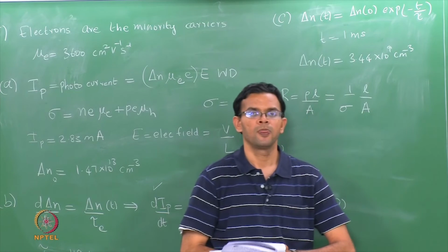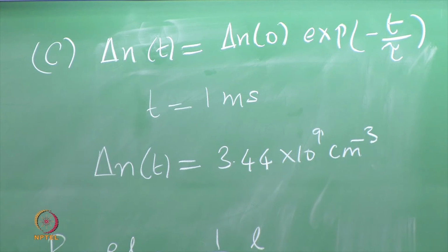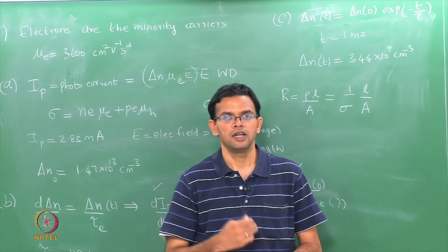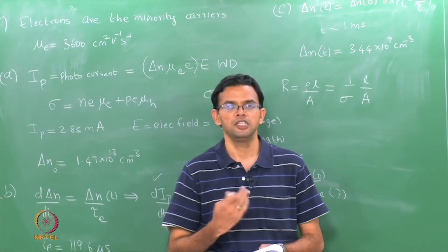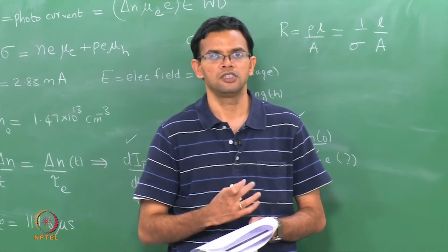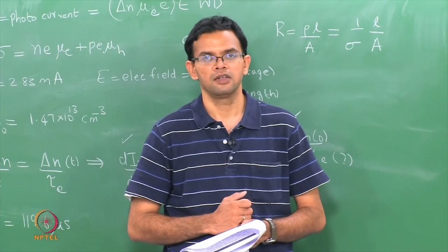per centimeter cube. Once again, we are assuming a condition of weak illumination, so that any change in conductivity is driven by the minority carriers. In this particular case, the change in concentration of the majority carriers, which are holes, is not significant enough to affect the conductivity.